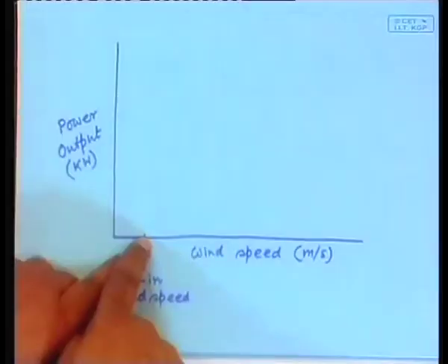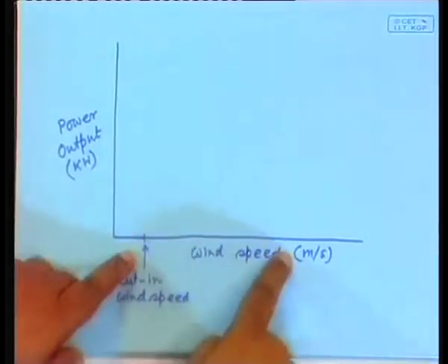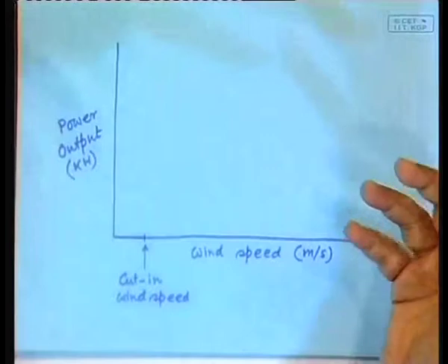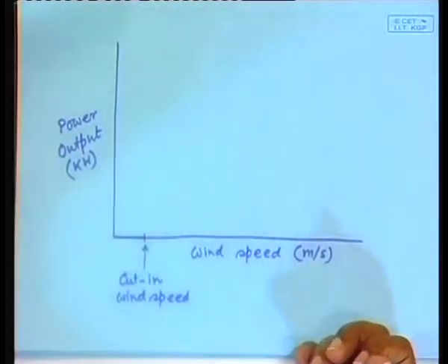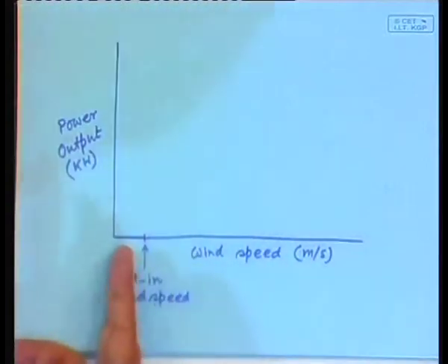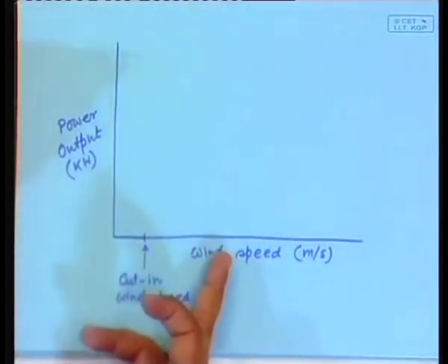So, what will be the strategy? Obviously, to extract maximum power. Now, if you extract the maximum power out of it, then what should the characteristic be like as you vary the wind speed? It will vary in proportion to the power contained in the wind, and the power contained in the wind varies cubically with the wind speed, right.